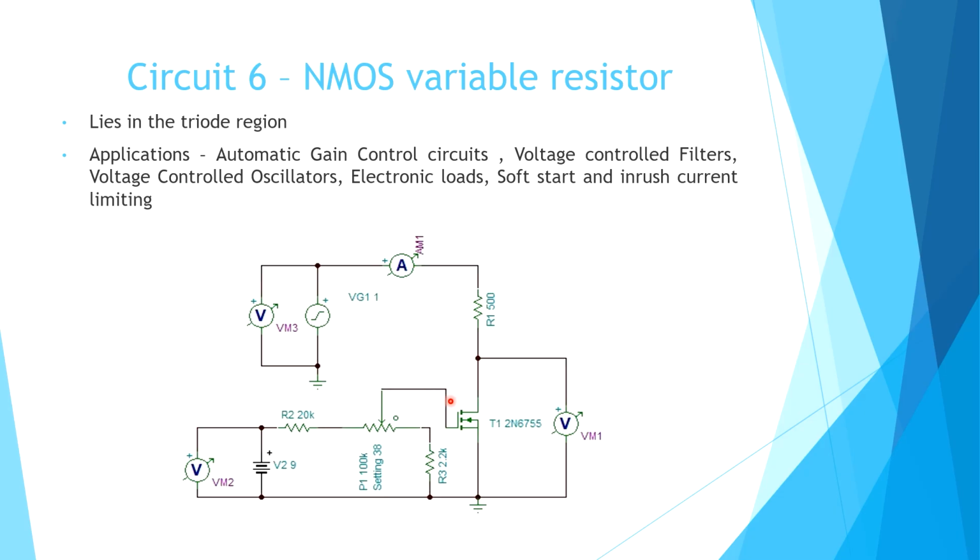So by replacing a physical resistor with a MOSFET and varying the gate voltage, the resistance is changed, so the cutoff frequency can be changed. Like that, we can change the cutoff frequency without changing any part of a potentiometer or any physical variable resistor. We can change the cutoff frequency electronically.